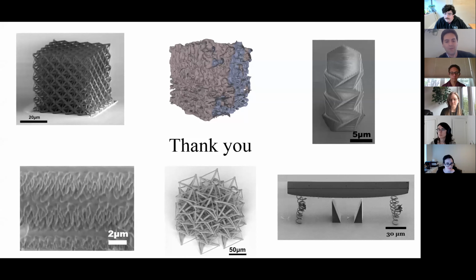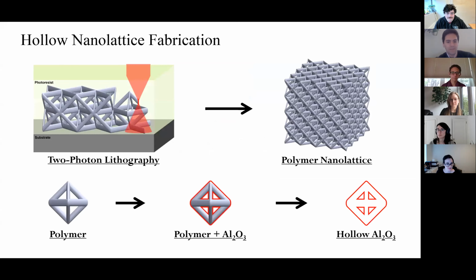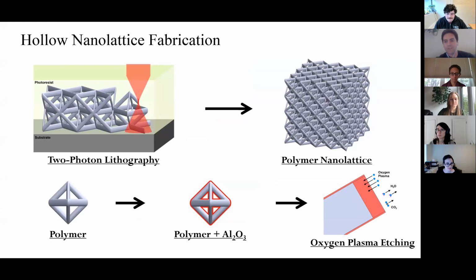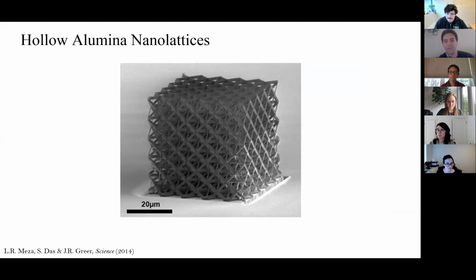Yeah, so, let's see, there we go. To cut out the structure, or to burn out the polymer, we use oxygen plasma etching. So we have a plasma asher, and we use focused ion beam milling to expose the very end of that structure. So you can see for this structure, there's actually trenches on the left and right side. So we just